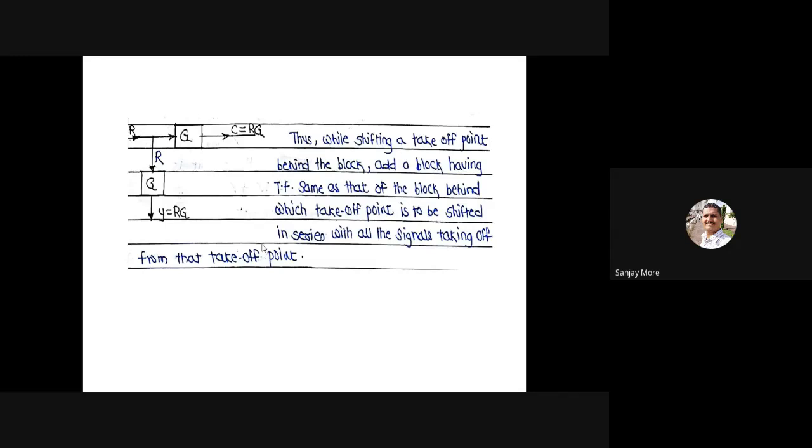Thus, while shifting a takeoff point behind the block, add a block having the same transfer function as that of the block behind which the takeoff point is to be shifted, in series with all signals taken off from that takeoff point. Okay.